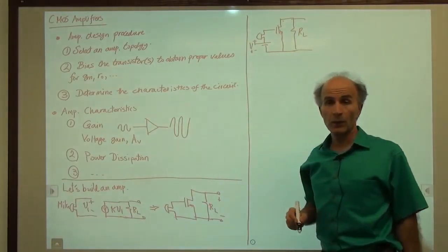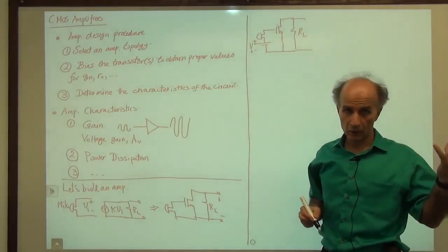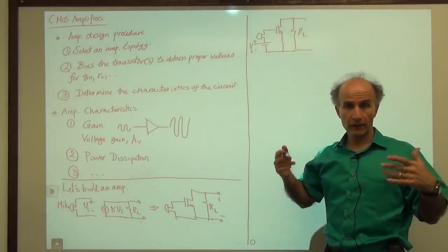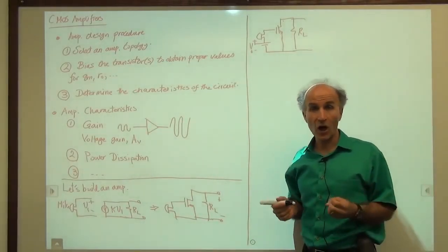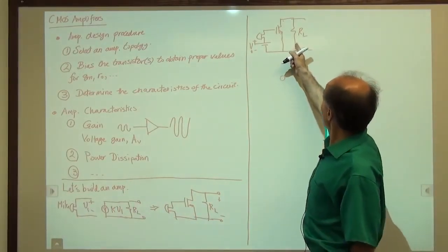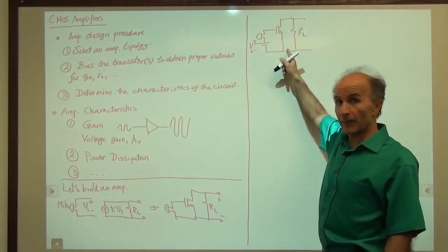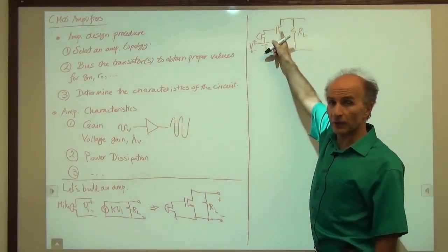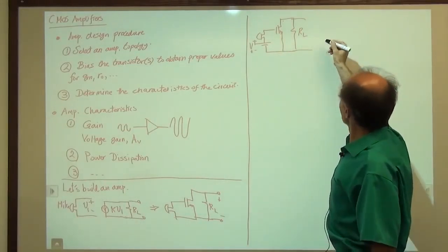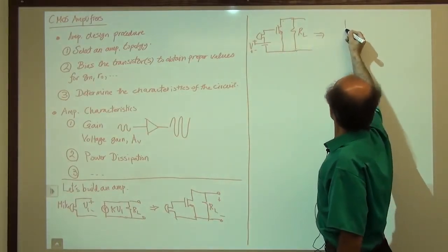So now, when the microphone has no signal, VGS is still equal to V0. V0 can be higher than the threshold voltage, so the device is on. But then we saw that we cannot have any current in this loop because there's no source of energy here, right? We need a battery to have current to continue to flow. So that didn't work. We said, okay, let's go and change it to this.